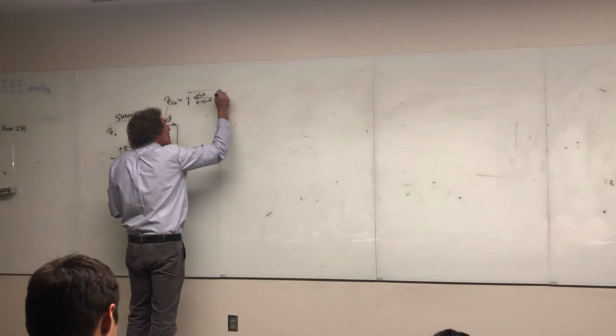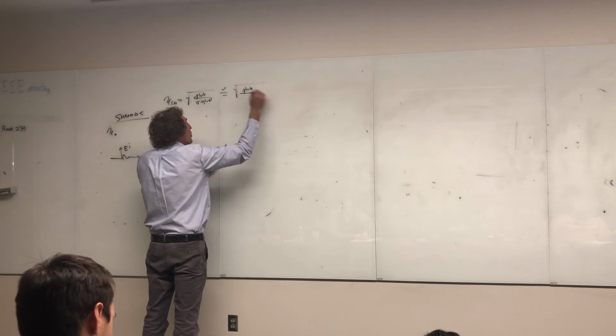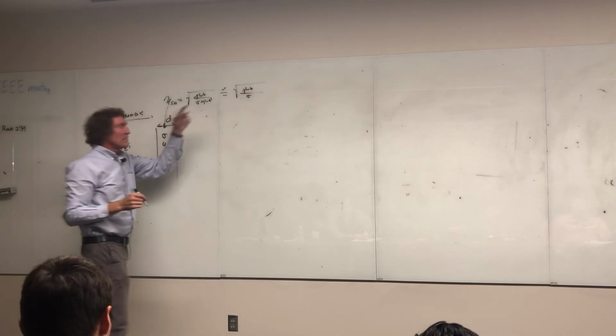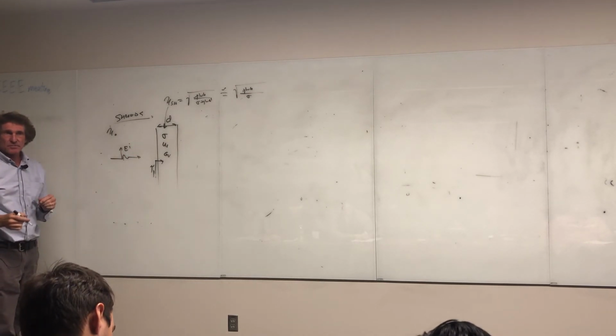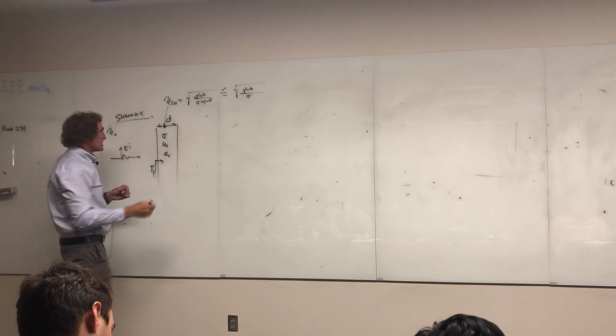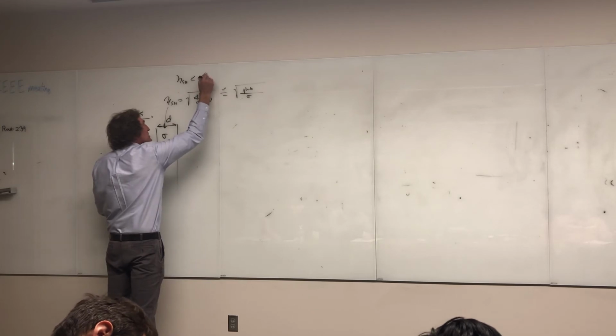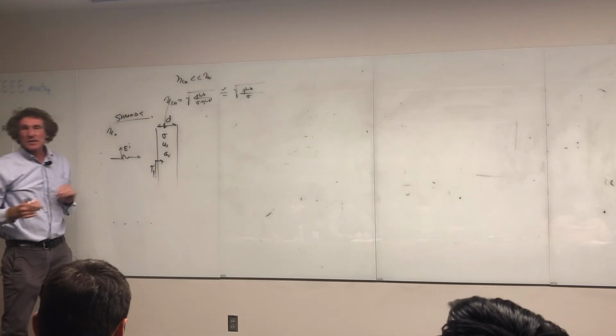Almost always this is simply the square root of j omega mu over sigma; the omega epsilon is usually of no consequence. Got me on that, everyone? The shield impedance is usually much, much less than eta naught. Eta naught is 120 pi.